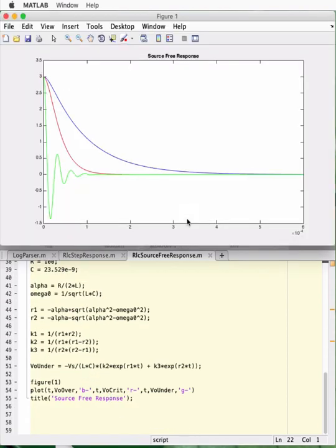And so if we plot all of these together, on the x-axis, I didn't label it in the script, but on the x-axis we have time, on the y-axis we have voltage. And all of the circuits start out at 3 volts because that's our steady state voltage level. The overdamped response, its transient response, has the same sort of exponentially decaying characteristic that we saw from the step. The critically damped response decays more quickly, just like it rose to the steady state voltage level more quickly.